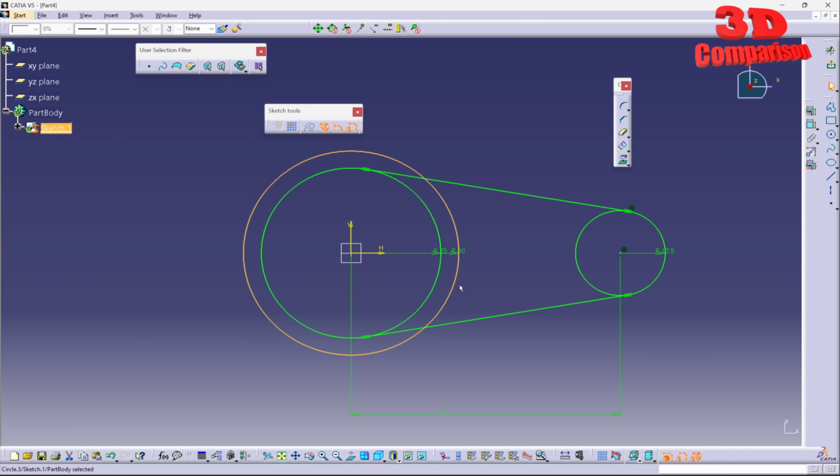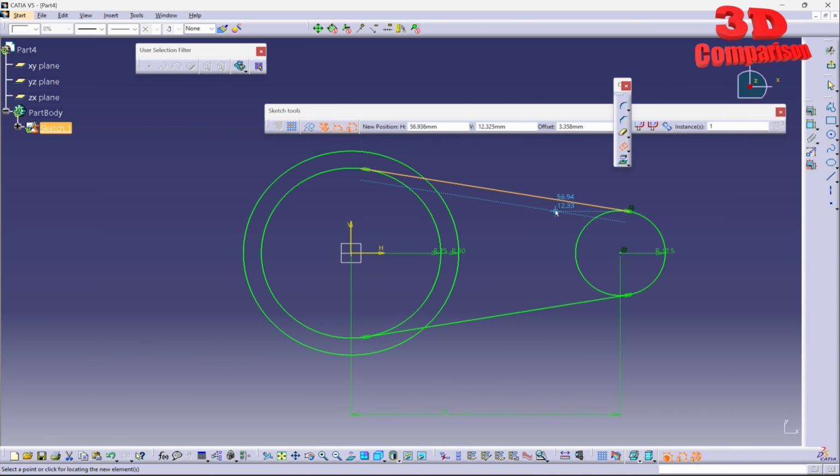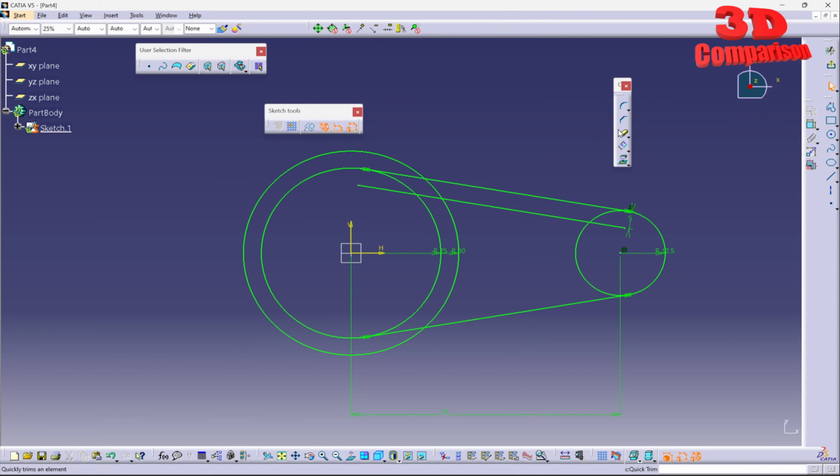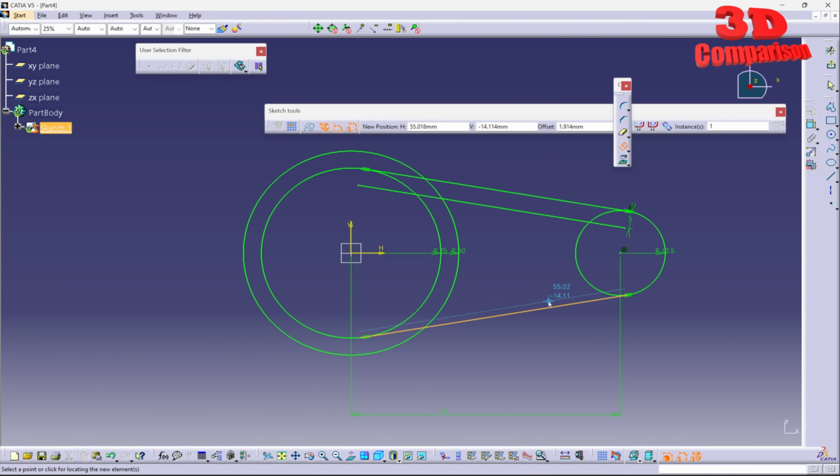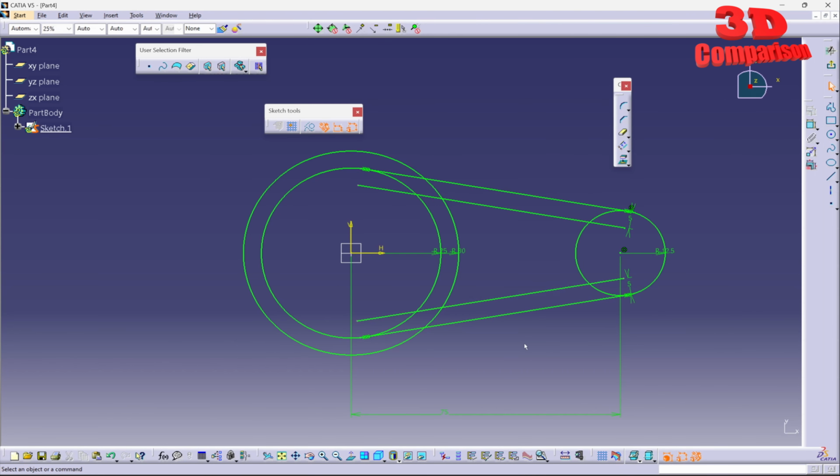So for people that are used to this, that isn't a problem, but otherwise it's quite tricky. So the radius will be 30 in this case. And now I want this to be offset 5 millimeters. I also want the same over here on the bottom, 5 millimeters. And now using the erase tool, I want this outer shape to be deleted. I will double click on this so we can better clear those sections. So we want all of those lines to be deleted.